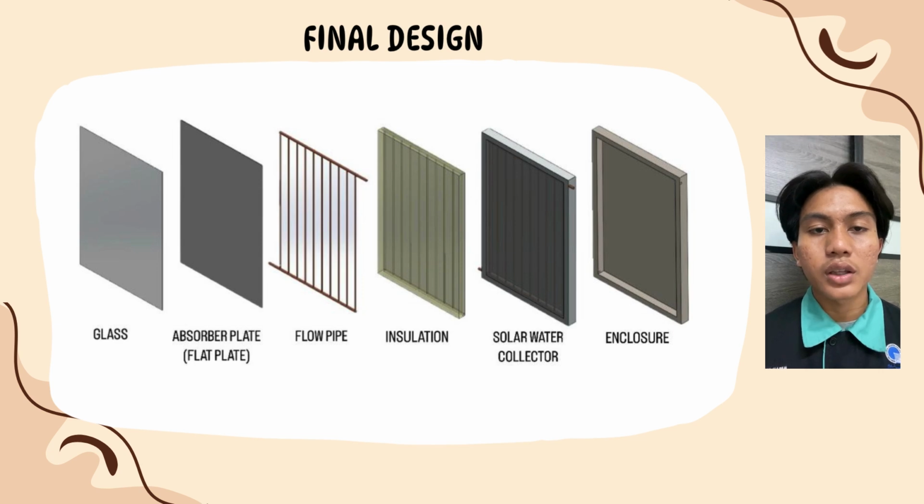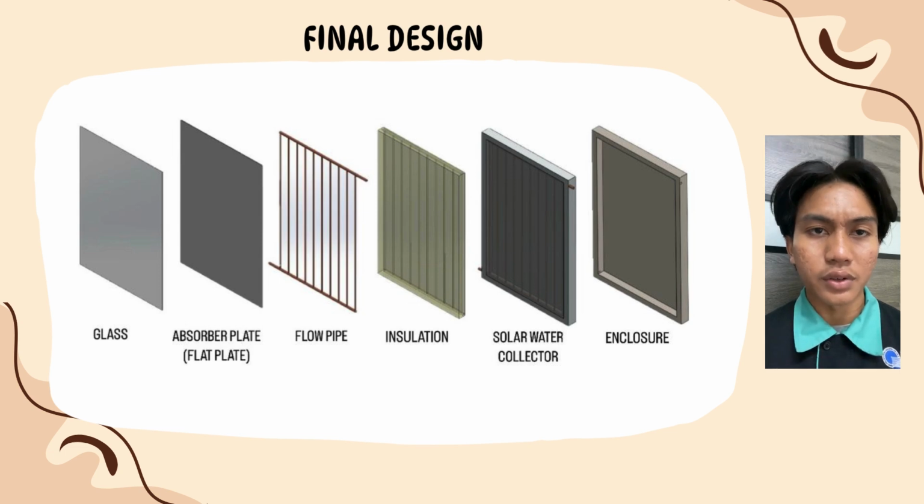We create a solar water heater using engineering software. The design allows water to flow smoothly from the inlet to the outlet over the absorber plate or flat plate to absorb heat efficiently. The main components include the flow tube and absorber plate, insulation, and transparent cover or glass, arranged to support effective heat transfer. This system is simple, reliable and affordable, making it suitable for home or small-scale use. We also focus on material selection, surface area and flow direction to improve thermal performance.